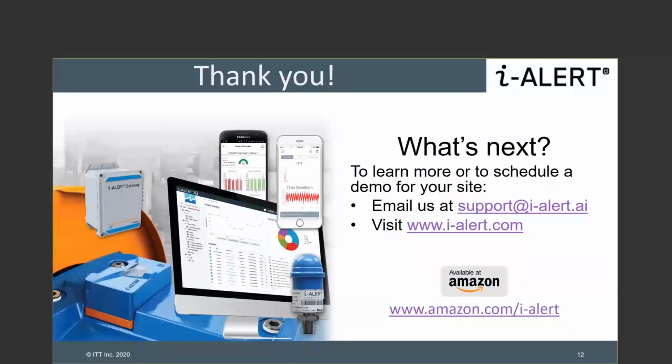And then in regards to the number of iAlerts, there was a question on, do you have to put an iAlert on the pump and the motor, one for each? It is better to do that. If you put one on the drive end of the motor and the driven end of the pump, that is probably the optimal setup. That's where most of the failures, bearing issues and things, will occur. Typically on the drive piece of equipment, the driven piece of equipment is where you will see the issues first. However, the drive end of the motor is also a good place to put an iAlert.